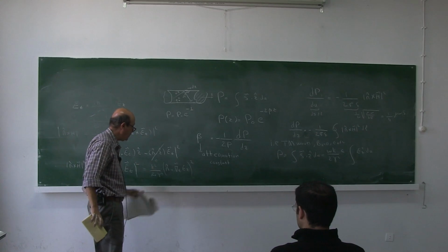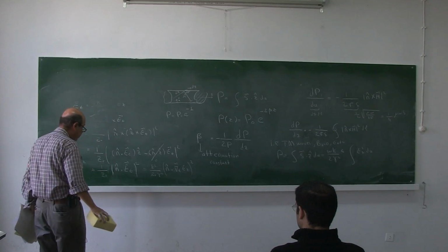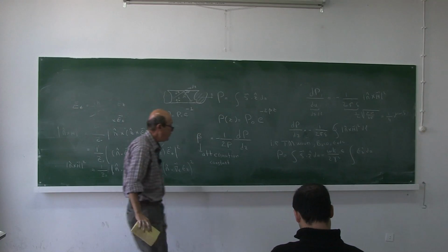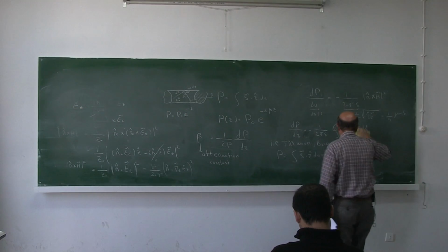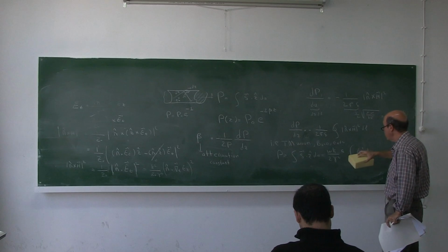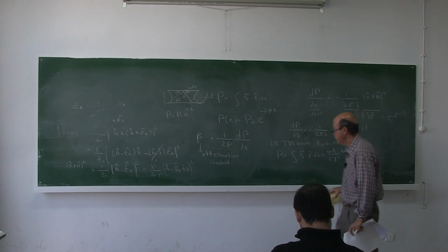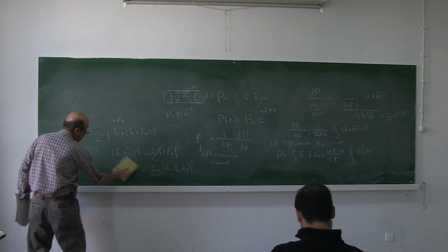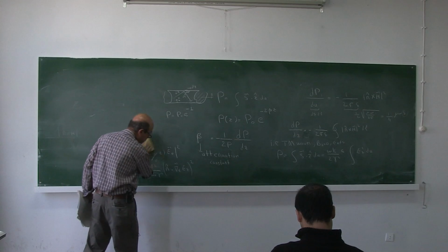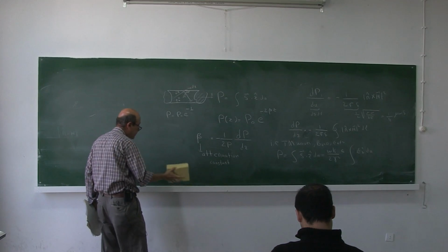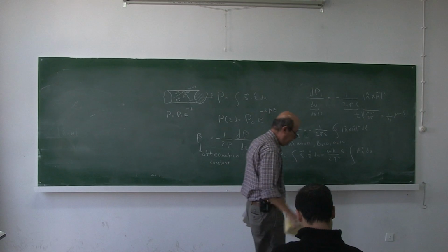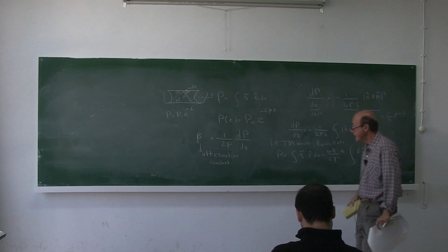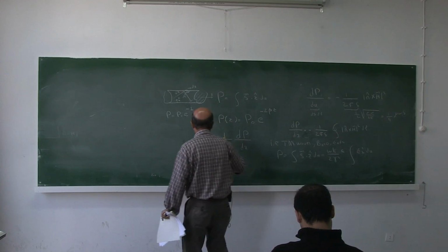You know how to calculate the z component of the field from the wave equation. Therefore, you can calculate n cross H. Once you calculate it, and integrate this value over the surface of the waveguide, you can find the power loss per length, and then you can calculate the attenuation coefficient. The attenuation coefficients for copper give a distance for a loss of power exponentially as e to the minus 1 at lengths of a few hundred meters.